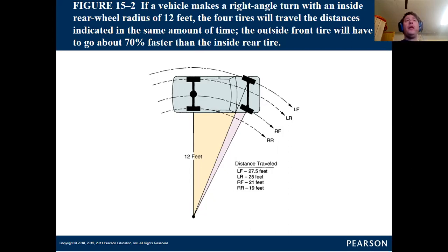The big picture here is, what is the vehicle capable of doing? Can we drive in four-wheel drive on dry surfaces, or can we not? Part-time four-wheel drive vehicles cannot drive on dry pavement. They can drive straight, perfectly straight, but as soon as you get into the slightest turn, you will start to have scrubbing and binding take place between the resistance between the front tires and the rear tires, trying to spin their drive shafts at different speeds.